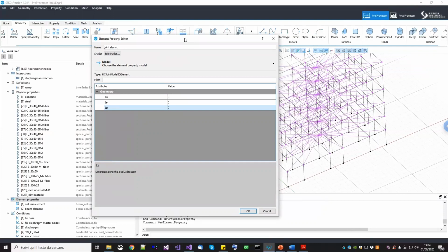So STKO will understand the size of the beam column joint directly from the size of the fiber cross-section converging in that node. Now, for the moment, you have to specify it. In this case, for the sake of simplicity, I'm going to consider an average size because I want to use the same joint for the entire model. So typically, the size of my beam column joints is 30 centimeters, 50 centimeters, or 1 meter for this kind of beam. So I do, let's say, a 0.4 everywhere. It is not correct, but if you want to be more precise, you can create more joint elements, of course.